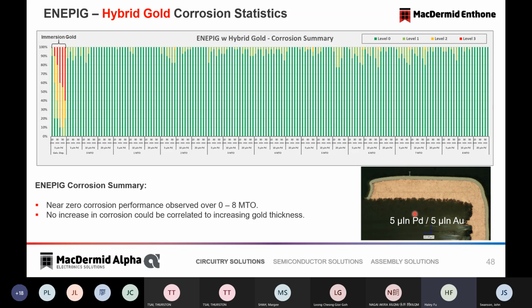His question is, those 2 finishes are preferred finishes for automotive high frequency, like 77 gigahertz radar applications. In terms of long-term reliability of exposed finishes, how do these choices stand up to sulfur-containing atmospheres, humidity, etc.? Does OSP coating provide some level of protection in the application?